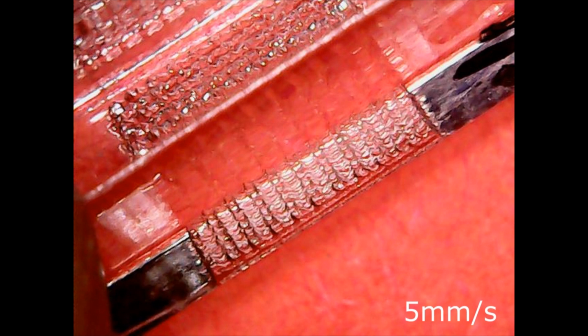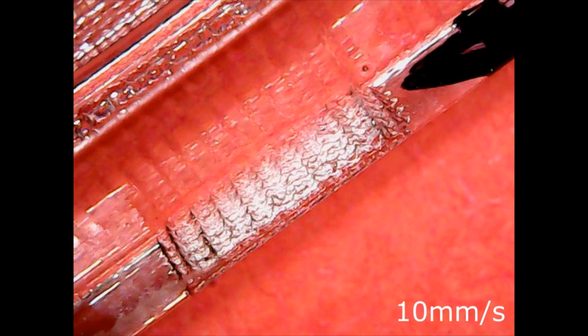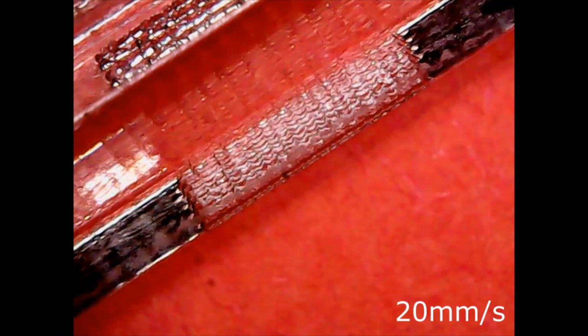Now, superimposed on that depth of cut, we've got these, what I suppose are motion spikes. Now, this is right down at 5 millimeters a second, where I would expect to see every single step of the stepper motor. Now, the second pattern at 10 millimeters a second is similar, but to be honest, there are a few less spikes in here. The depth of cut's about the same, but yeah, it's not completely uniform. 20 millimeters a second? Wow. The spikes are beginning to disappear.